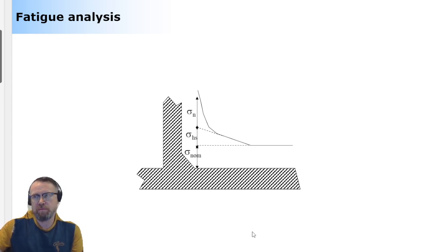Geometry. What happens because of the geometry is that when you take a close look at the stresses very near where the crack is growing here at the welded toe, the stress starts to increase quite a bit. This is because of the non-linearities in a structure, and this causes the stress to go quite high. Another not great thing, because this is another reason that the fatigue in a welded structure is quite a serious